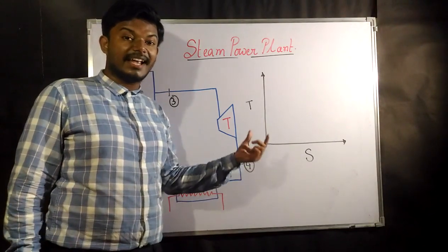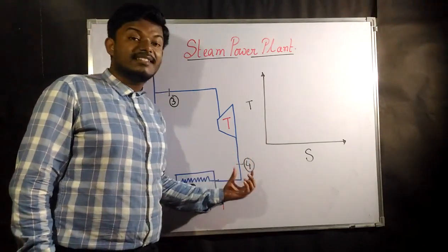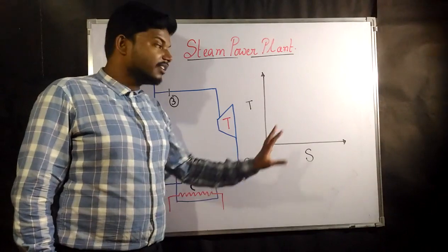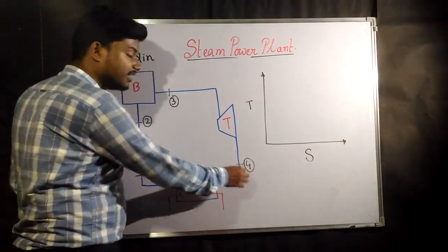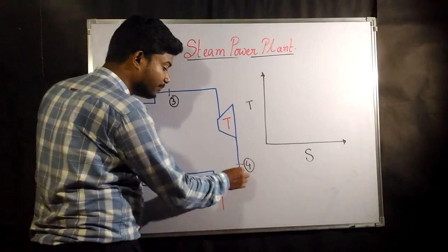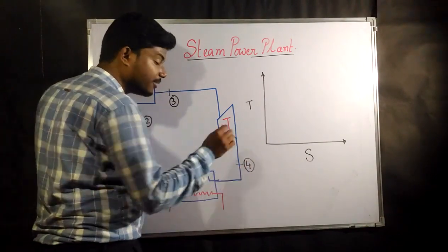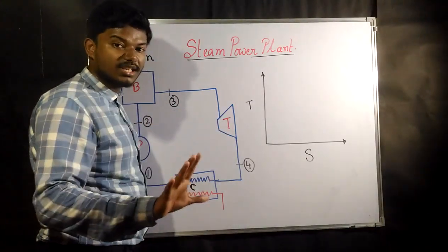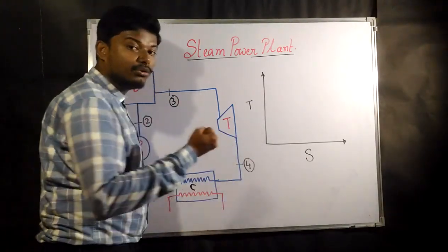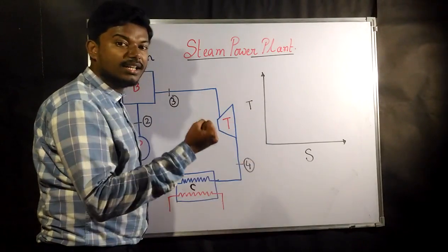But if you apply the Rankine cycle, then this is going to be saturated vapor. So you remember that only vapor you can take. If you apply the Rankine cycle, it will come out as saturated vapor, or the conditions will be given in the question itself. Either it can be liquid plus vapor or only vapor.